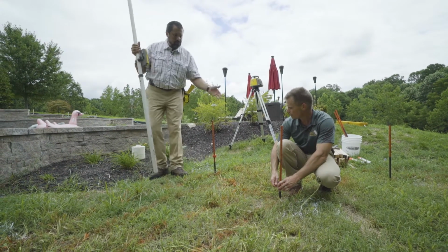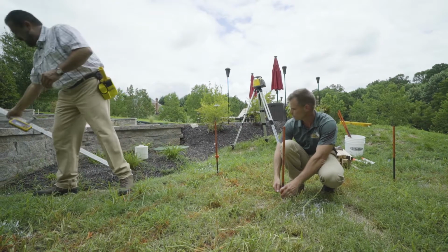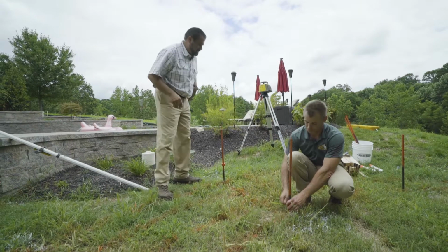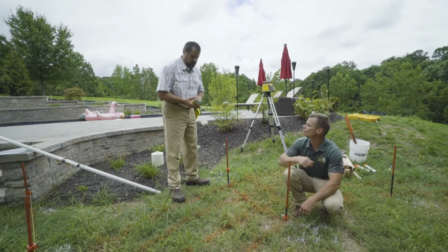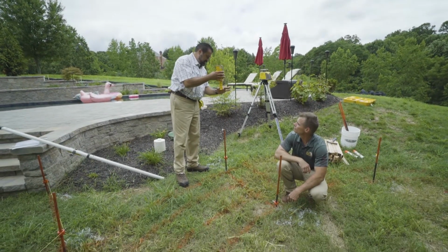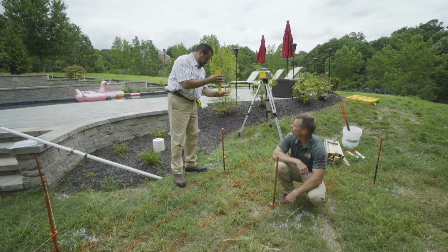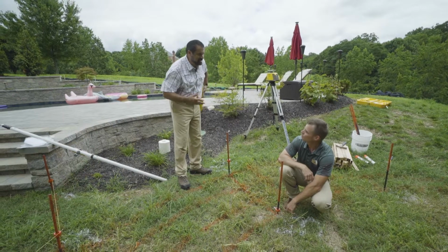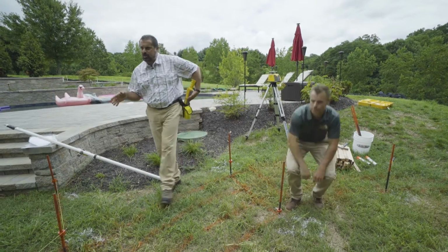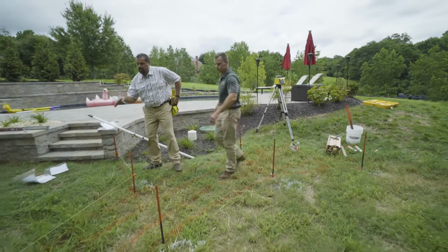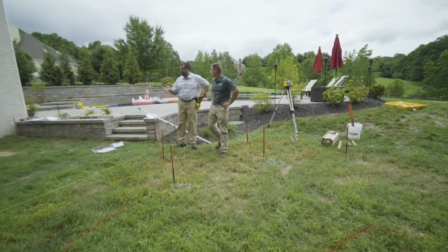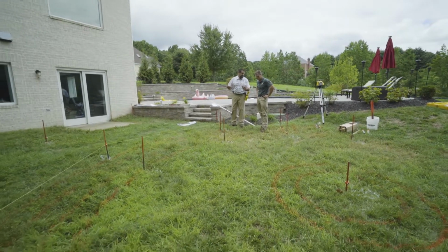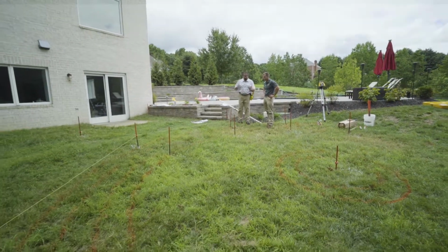Okay, now, we used a laser level and a stick to get those pins set. And sometimes that's easy because it's easy to work from those pins. We could have also used the handheld unit and just shot that down. Bang right on. Beautiful. I'm good. Yep. Right, so it works exactly the same way. Very good. Our upper area is already set up. So we're staked, we've got our line collars in, and our string lines are up. Now we put them 6 inches above finished grade of pavement. So they're really out of our way as we're working.